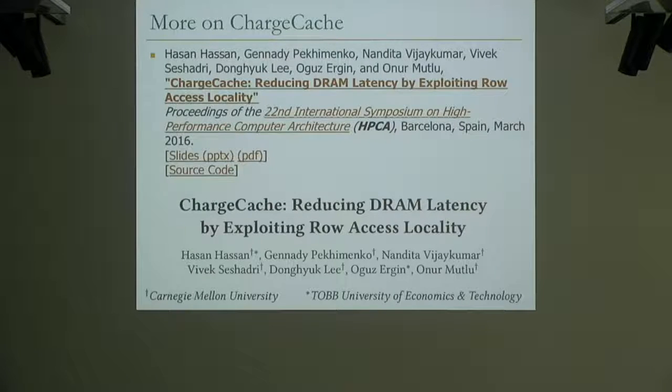I see. Yeah, certainly it depends on what you're executing, right? It depends on the program. If the program is accessing a particular data structure within 8 milliseconds, then you capture this locality. Assuming, of course, it leads to all of these bank conflicts at the bottom. But if the program is accessing the data structure every 9 milliseconds, then you're not going to capture that locality.